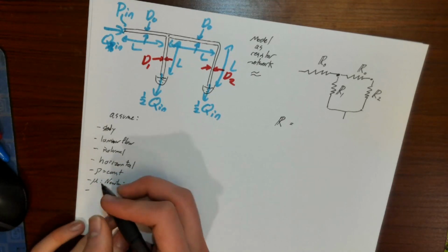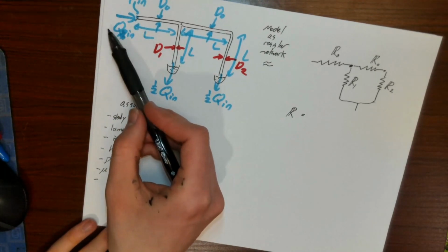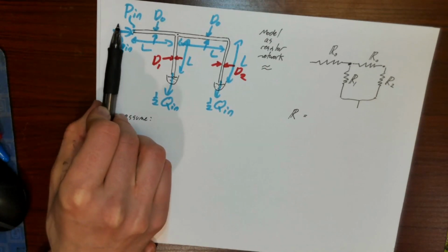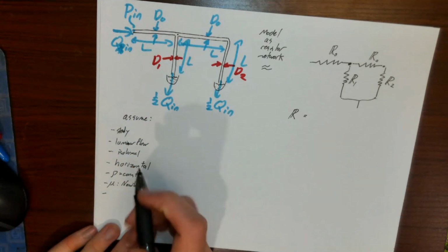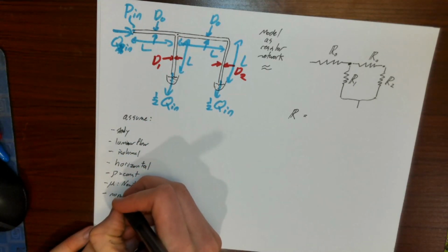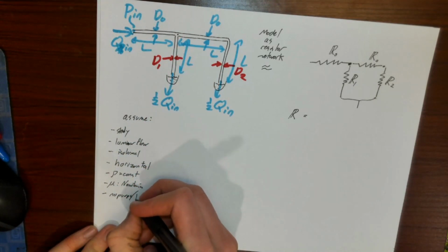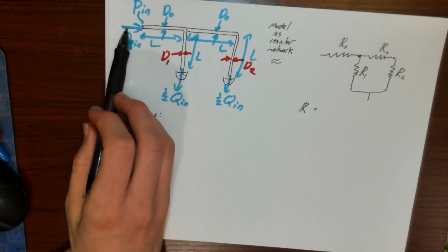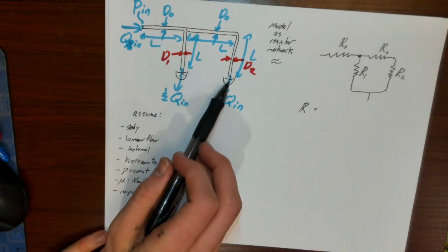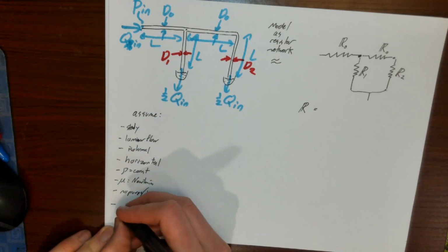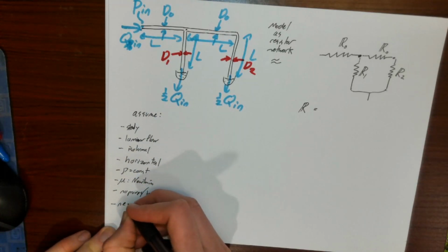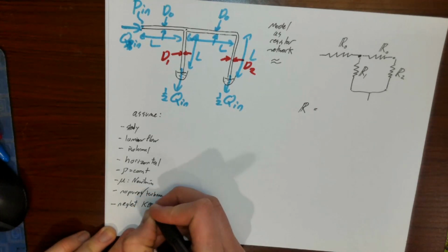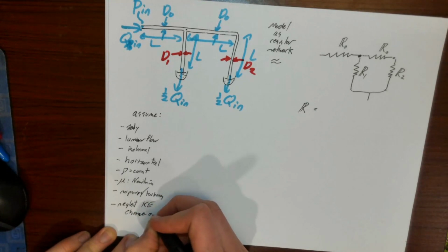We know that this system is going to need some pump to drive it, but the pump is somewhere upstream of this part of our system right here. So we basically have no pumps or turbines. And, strictly speaking, we have some kinetic energy of the fluid coming in and some kinetic energy of the fluid going out, but we're going to neglect the kinetic energy change of our fluid.